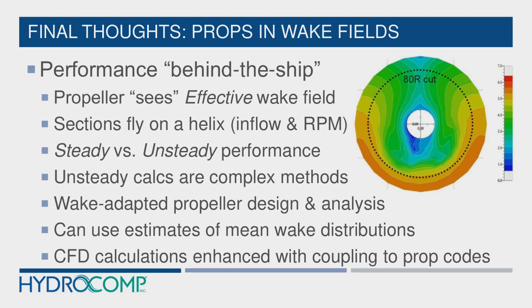So, has that velocity had enough time for the propeller effects to migrate upstream, or is it a really quick snapshot? If it's an immediate snapshot, it almost is a nominal wake fraction.